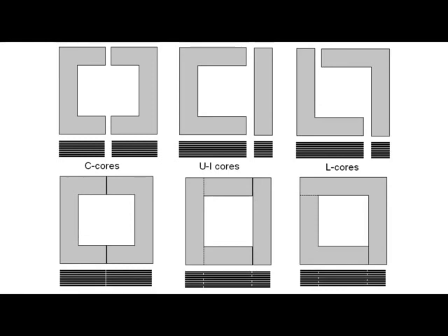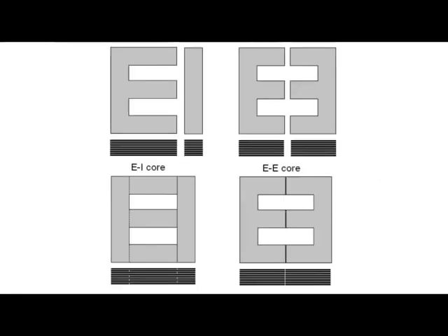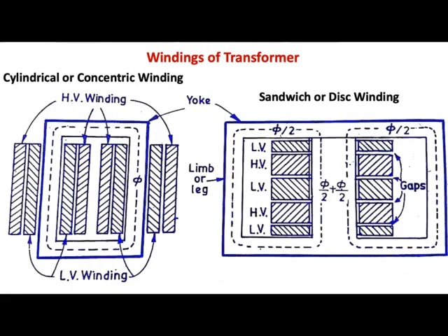L sections, we can just rotate by 90 degrees and rotate the air gap so that it is uniformly distributed. Then EI section, one side E and I. So next surface, the I will be on the left side, E will be on the right side, and so on. Basically, it is to not have the air gap at one place. So that's the reason we keep on changing.